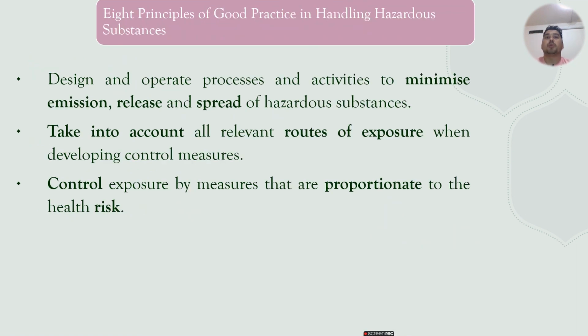8 principles of good practice in handling hazardous substances. These are the 8 principles that we can use whenever we are handling any hazardous substances. Design and operate processes and activities to minimize emission, release, and spread of hazardous substances in the environment. Take into account all relevant routes of exposure when developing control measures. Control exposure by measures that are proportionate to the health risk.